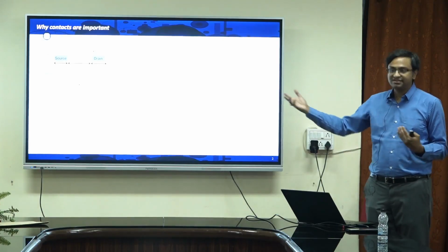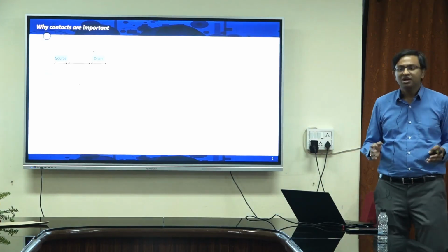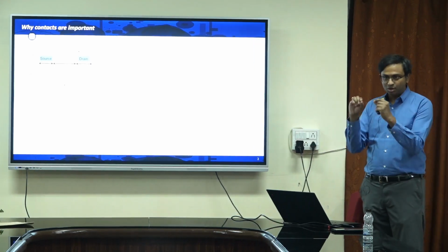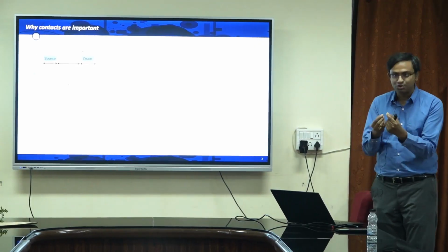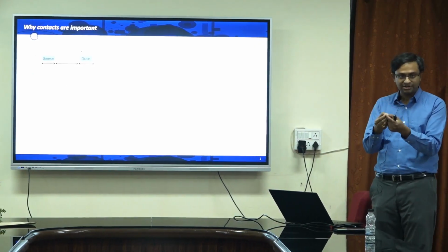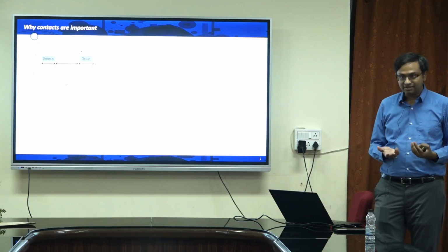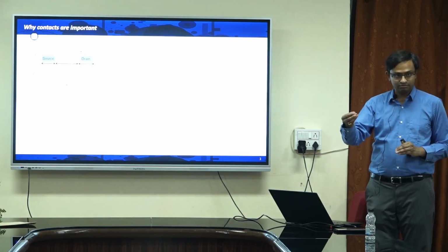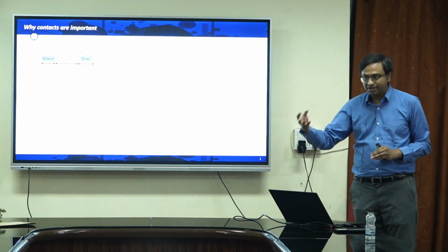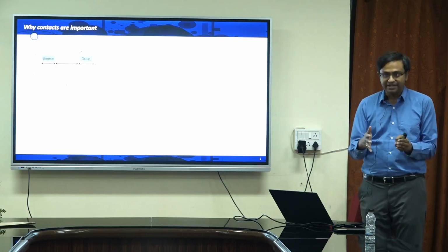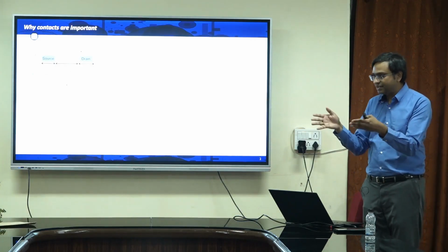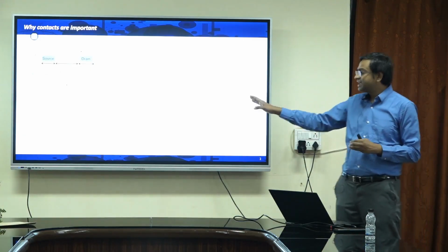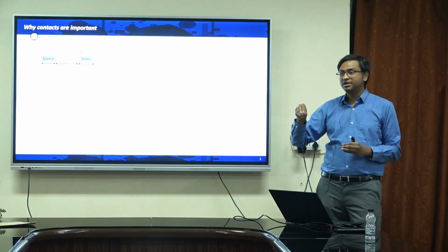And then the RSH is the sheet resistance. So this is very similar to resistivity, but because it is a nano sheet, there is no defined thickness, so we club those two things, the resistivity and the thickness, together into this quantity called the sheet resistance. And the sheet resistance is a property of the material, and the rest are all geometric factors, because this is something you are designing. You have full control over what channel length of the device will be, what is the width of the device will be. So these are design knobs, while RSH is a fundamental property of the material that you are using.